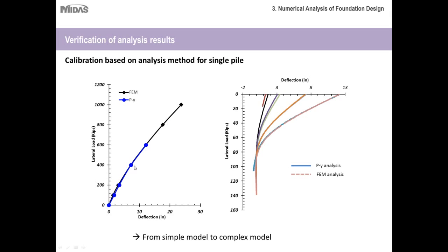From this simple analysis of one pile, you can then go on to a more complicated analysis with several piles put together and capture the results for the same. So basically the comparison of FEM with PY analysis is also important at times, because you have to calibrate your model with the realistic data, and sometimes the realistic data could be erroneous, so you have to be on your guard based on the field test results and the results that you are getting.